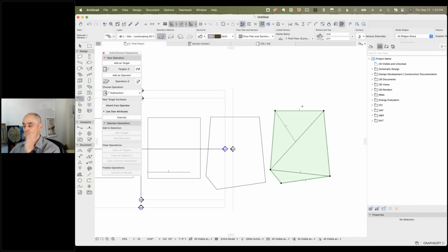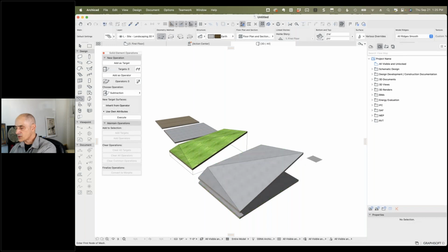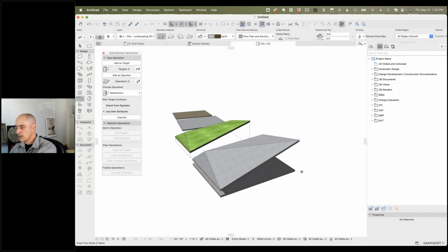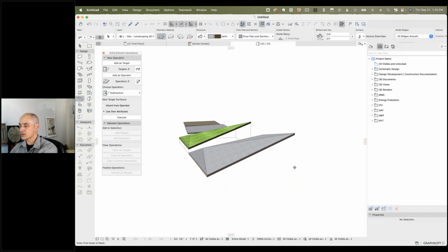You'll notice that we saw something appear here. And if I go to 3D, we'll see it looks different than it did. And if I take this mesh here and delete it, you can see that it has created the roof pieces that have the exact same geometry. It looks like it's creating one at the bottom as well. I don't recall it doing that in the past, but maybe that's just part of the functionality that they've put in. Obviously, I get rid of that, and then we have now something that has a uniform thickness.